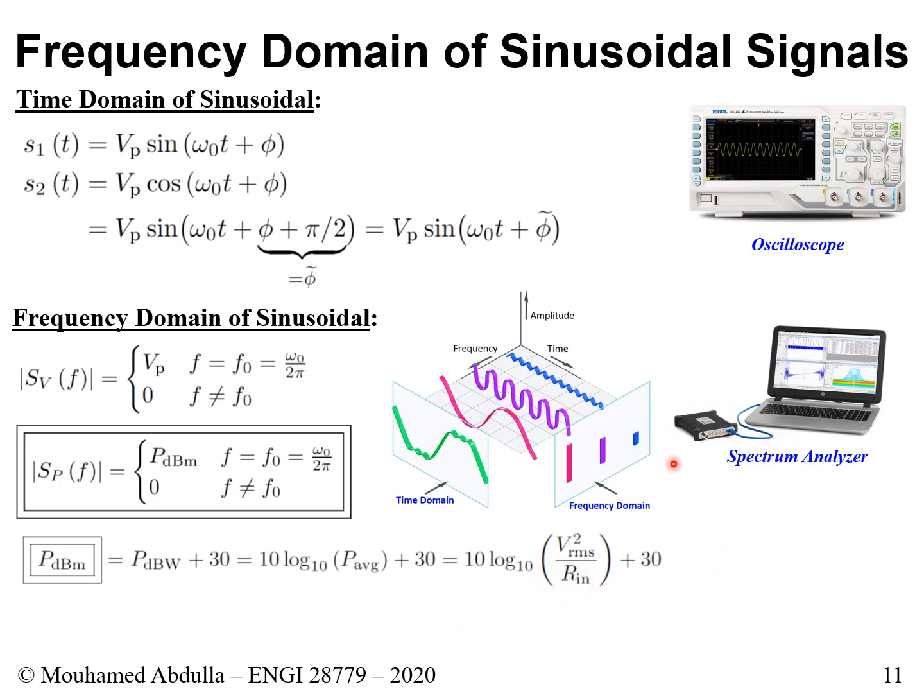This thing here, the internal resistance of this thing. And we said generally it's around 50 ohms, according to the data sheet of the Tektronix one. But if you have a Rohde-Schwarz spectrum analyzer or a Keysight, you could just look at their data sheet, and then whatever it is, you put it here. By the way, when I say Rohde-Schwarz, Tektronix, or Keysight, they have many of these spectrum analyzers. You have to look at the specific one that you are using, right? So there are many of them.